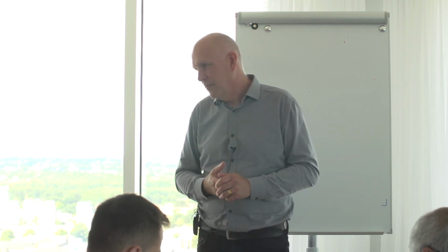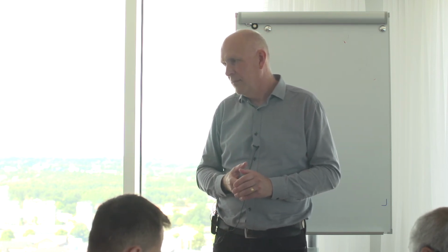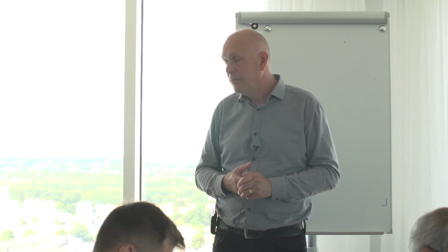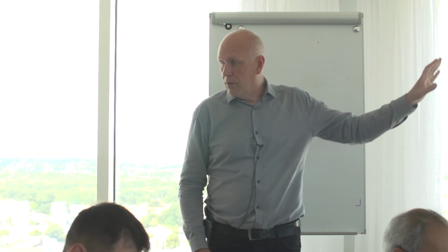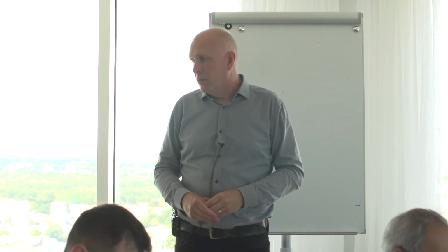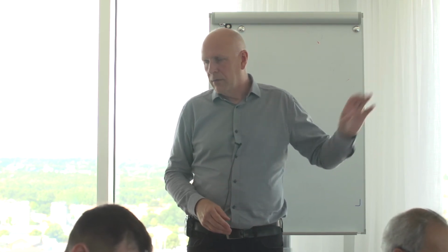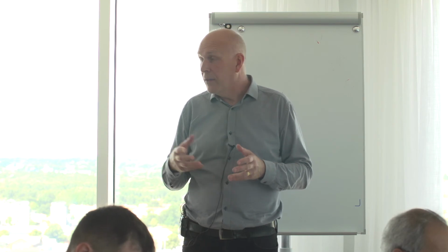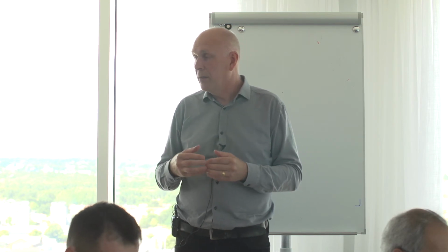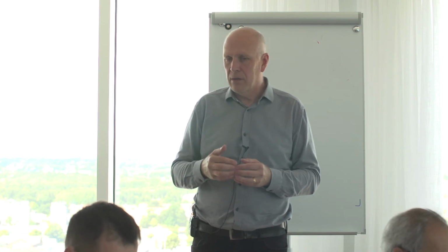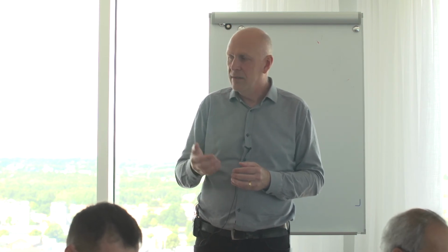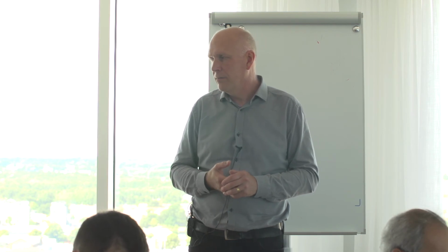Yes, so I think the verification steps are also very important. Yeah, but the verification step is more important on the flight critical side than on the mission critical side, of course. But there is, of course, a lot of verification to be done also there. But we don't have the requirement on independent testing, for example. So the same engineer that developed the application can also be included in the test team, in the test activities.